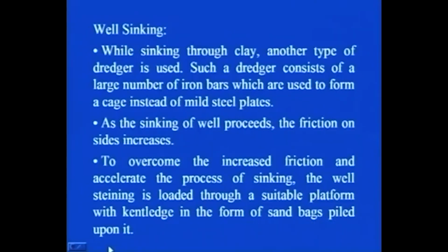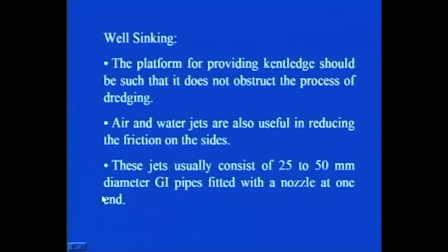So we increase the load on the well steining with the help of a suitable platform with kentledge. The platform for providing kentledge should be such that it does not obstruct the process of dredging. So a suitable arrangement has to be made so that dredging as well as sinking goes on simultaneously.